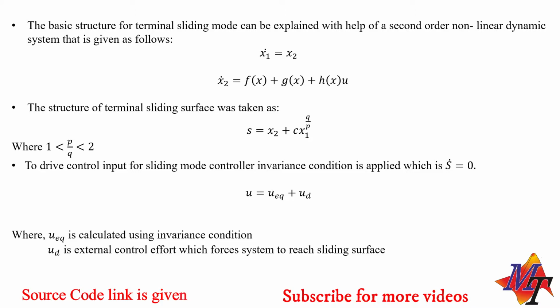The basic structure of terminal sliding mode control technique has been explained here, where a second order non-linear system is taken, where x1 dot is equal to x2 and x2 dot is a function of system states as well as u, that is the control input. So the structure of the terminal sliding surface looks like x2 plus c x1 to the power q by p, where q by p is a power term. While designing a sliding surface like this, we have to make sure that p by q lies within the 1 to 2 range only.